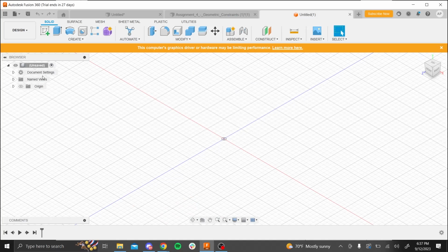So here, I'm just going to press the show button, but you can see these orange squares here. Those are your planes, right? And when you make a part, you start with 3 planes, like the X plane, the Y plane, and the Z plane, right? But there are times where you want to reference somewhere else.